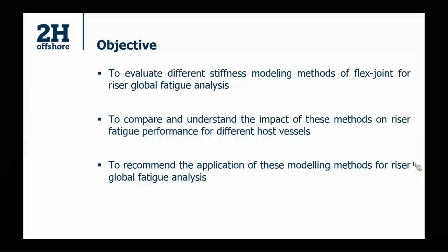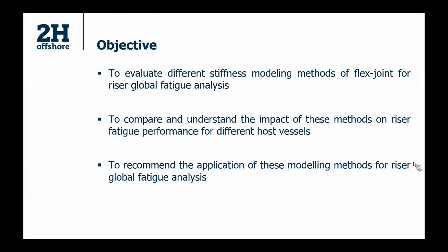The objective of this study is to evaluate different stiffness modeling methods of flex joint for riser global fatigue analysis, and to compare and understand the impact of these methods on riser fatigue performance for different host vessels. We believe different types of vessels have different motions, so it should make some difference. And at the end, we will give recommendations on the application of these modeling methods for riser global fatigue design.